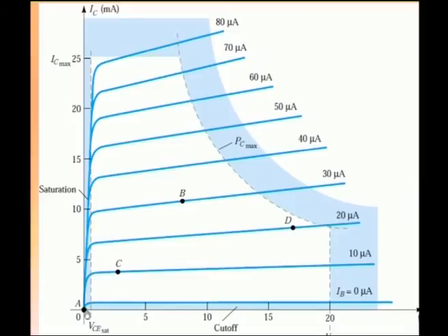What is this point A? This point is located at 0 level. Before biasing, we did not give any bias to the circuit. So, if you choose this point there will not be any change in the output with respect to the input because it is already at 0 level. So, we have to give bias to the transistor first.